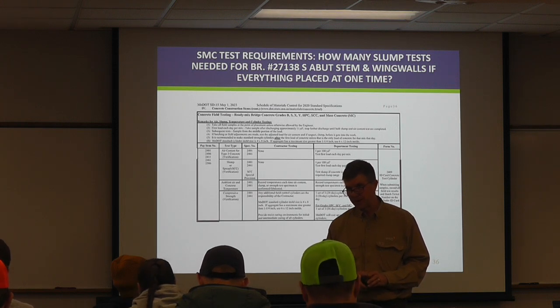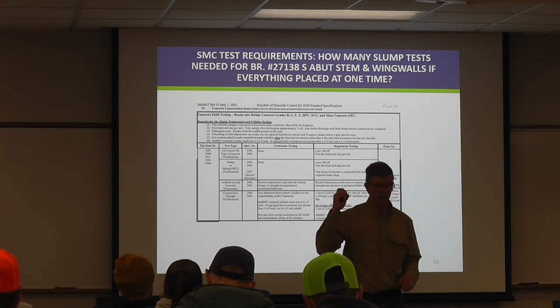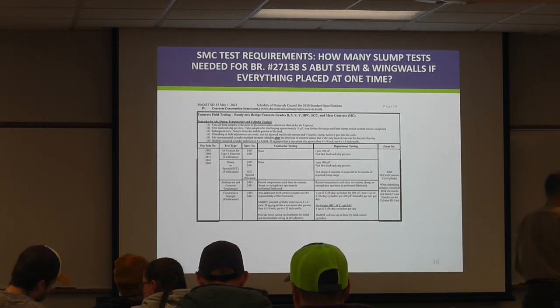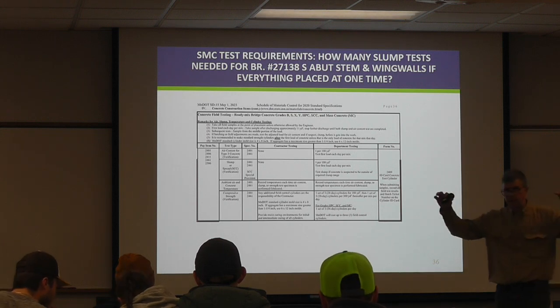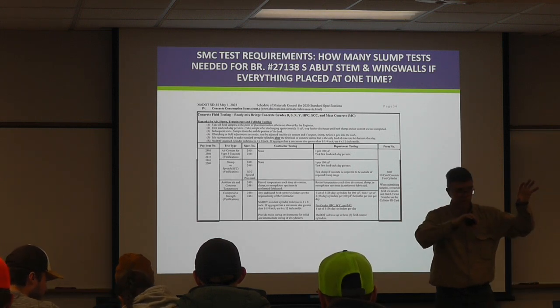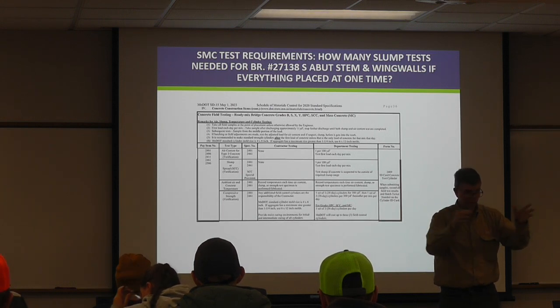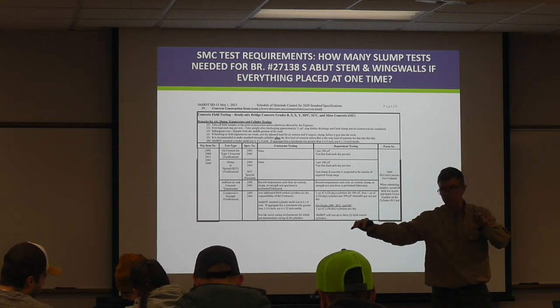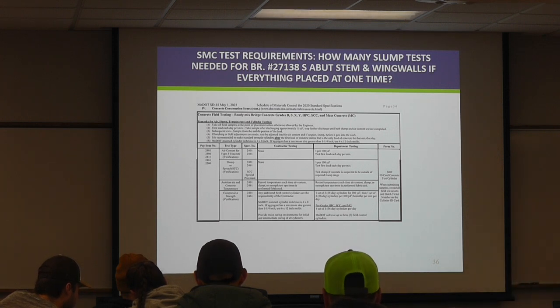So if you have multiple pours, the way the plan is set up, we're going to have at least 4 pours and probably more, because of the need to put the construction joints in. Although what they could do, and oftentimes they may form everything, if it's 4 pours, say pour 1, 2, 3, and 4, today they might do pours 1 and 3, leave that gap in between, and then 72 hours later do pours 2 and 4.